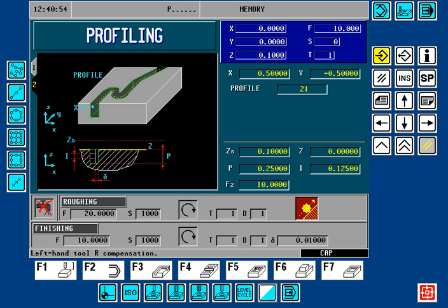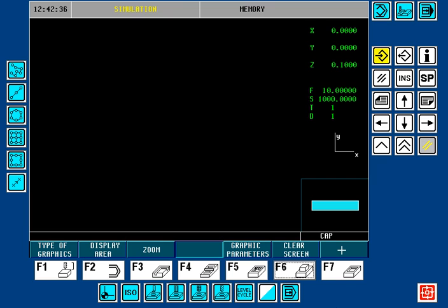Another tool that I like to use when diagnosing a step and path error is the cutter comp control. Here we have the icon for left cutter comp. If I change the 1/2 key, I can change that to center path of tool, which means there is no cutter comp. I'll again go to the graphics icon key, and I'll run this project with the 1/2 inch tool diameter that I previously had. And you can see that it runs center path of tool just fine without the error.